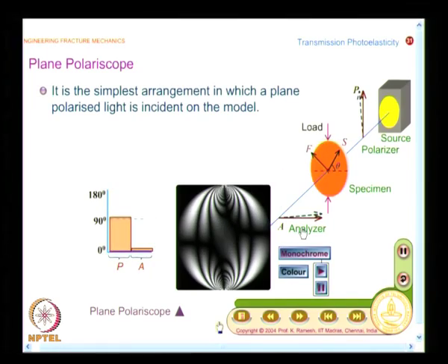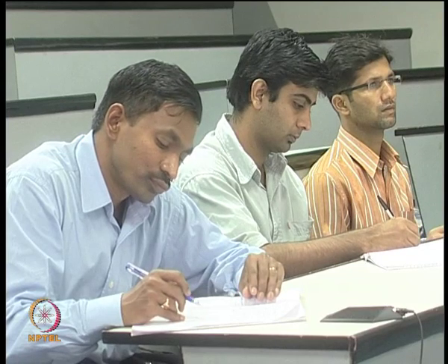For a plane polariscope, trigonometric resolution is also needed, because that gives you an understanding of what happens in each optical element. We did the logical explanation, we did a trigonometric resolution, and we will also analyze the plane polariscope by Jones calculus. The reason is, you understand all the three methodologies. A logical explanation may not be possible when I have many optical elements. Many optical elements will complicate your logical explanation. So, we will see what happens in a plane polariscope.